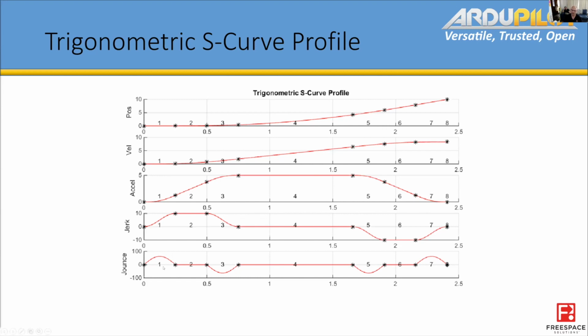We can look up that ATC accel limit and define what a maximum jounce or snap is. This jounce, snap, it's the same thing. Same with our maximum jerk, we can define it based on our maximum roll or pitch rate that we're allowed to achieve in the attitude controller. And our maximum acceleration can be directly taken from our maximum lean angle that we allow.